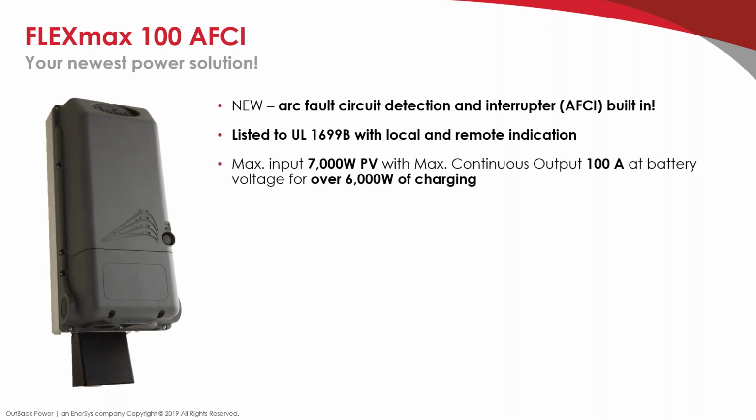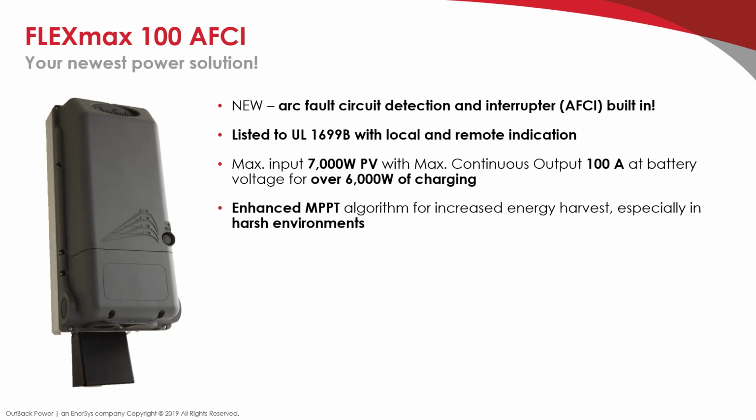Maximum input is now 7,000 watts with maximum continuous output of 100 amps of battery voltage for over 6,000 watts of charging. That's a nice update there. We've expanded the input capacity to allow for more solar on the charge controller under warranty. And again, we've enhanced the MPPT for increased energy harvest, especially in harsh environments like I mentioned. Rated for maximum PV of 300 volts, so this is the same as the previous generation.